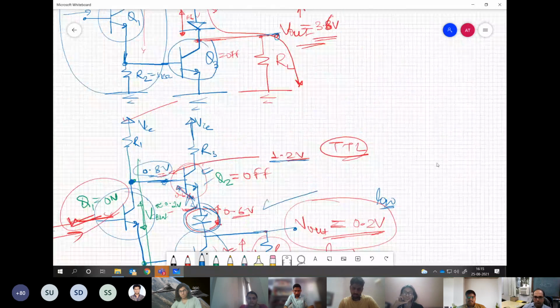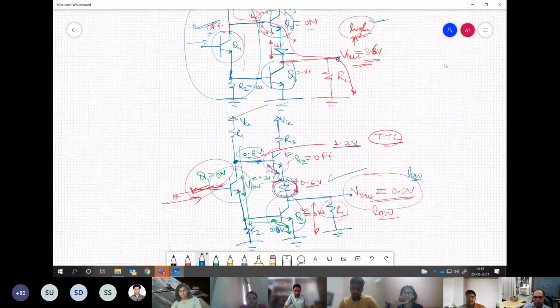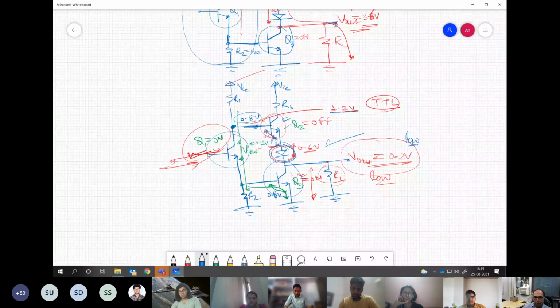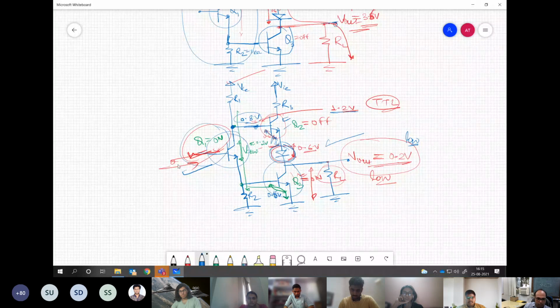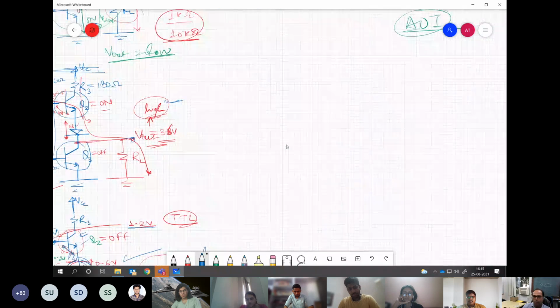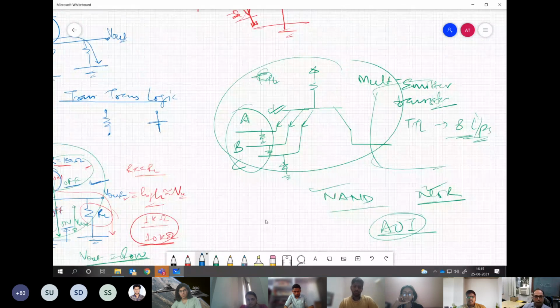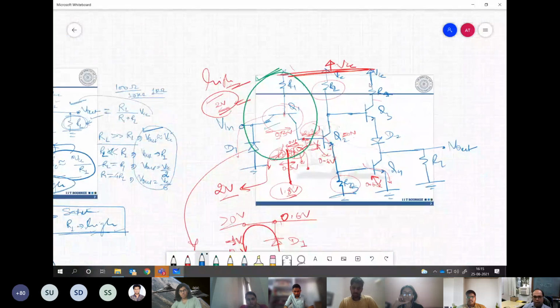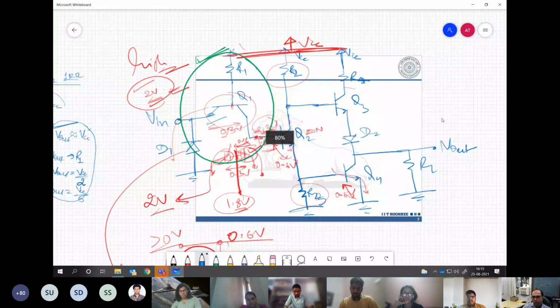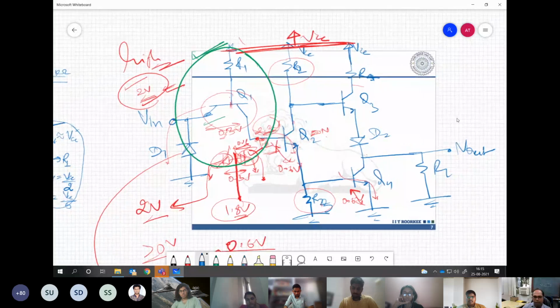Now for the input, what we have to give to this first transistor, on the extreme left-hand side. So here, how to turn this on? One way could be to connect a base resistor and apply the input voltage. That could be okay. There is no problem in that. But there are some better additions in this technology which make this more convenient, even if we want to add some more inputs.